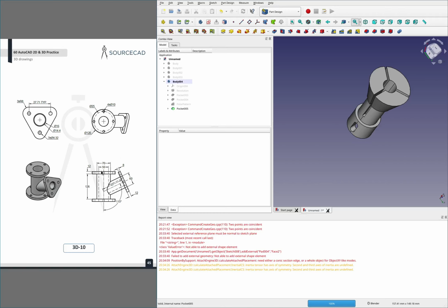So I mean, what you would do is, you'd make this kind of a regular pipe as you normally would, and then you make a kind of funky plane off here out in space to dimension this bit, and then you extrude that back, and then you just cut 2 of these holes in, and you call it good.